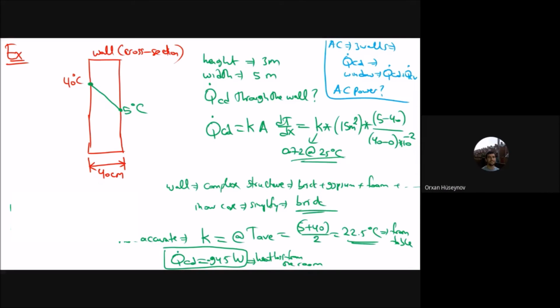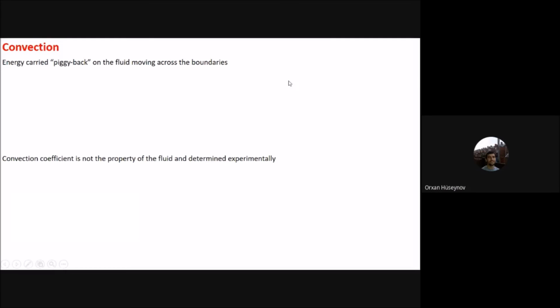or heating capacity. But one thing you should notice here is that you can neglect the floor, because we are assuming that the heat loss from the floor is very small. But you can do a more detailed analysis, not neglect the floor, and also add the roof part, and get the amount of heat transfer from the room. And from that amount of heat loss, you can determine the capacity of the heat pump required for the location. Okay. So the next part is the convection.